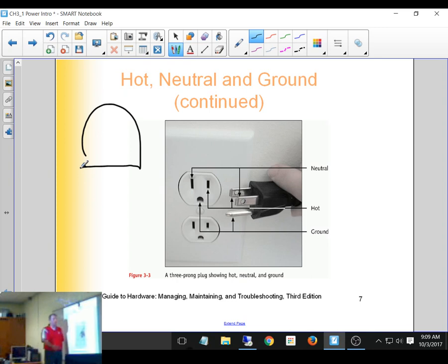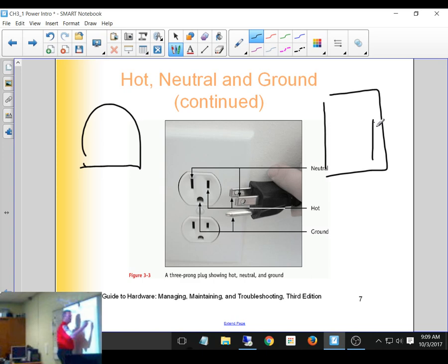All those wires go into your electrical panel at one spot, and your electrical box has a wire that runs out to somewhere stuck down in the ground. That ground is there so that any over voltages go somewhere other than you or your house or whatever else is plugged in. Without grounds, many electrical things are in danger. And we're going to talk about things that help protect us from electricity and electricity problems today, and none of them work without a ground.